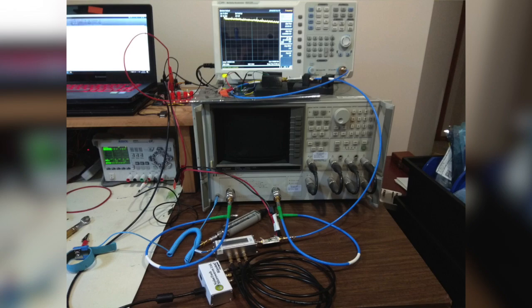validate your setup. So if your spectrum analyzer starts showing you warnings like ADC over voltage or input power exceeded, you're probably going to want to turn attenuation back on, raise your reference level, maybe turn your preamplifier off. That will require recalibrations of steps 1 through 8, but if you consider it ahead of time, you won't have to redo it. So perhaps it's something you don't find out until you actually add the device under test into your setup. So maybe we should include this in some of the earlier steps.